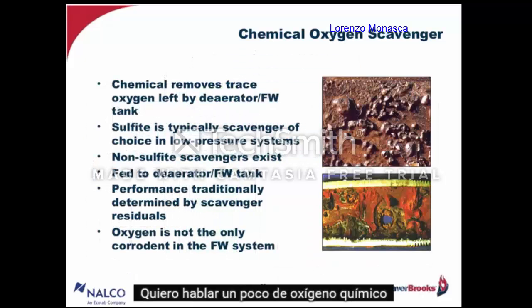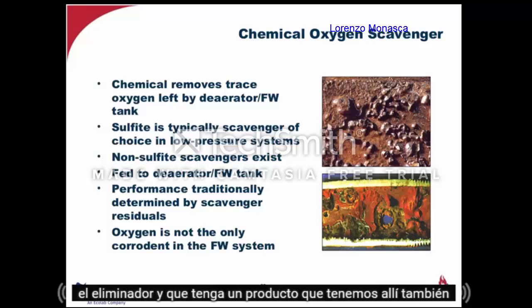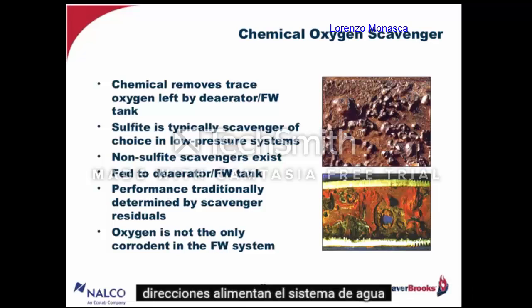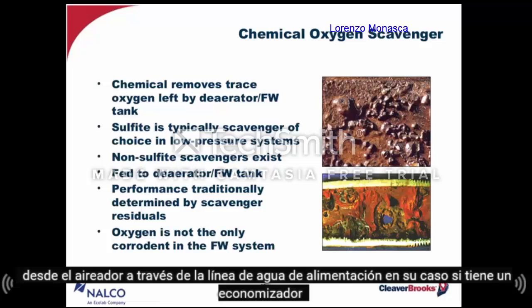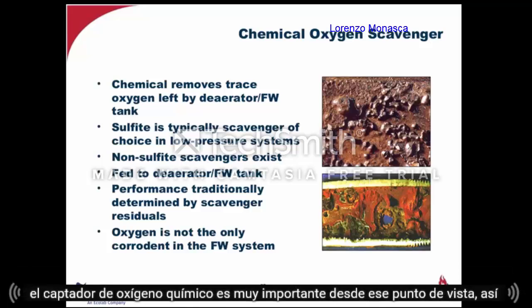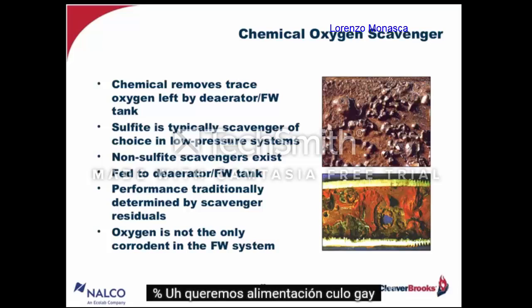So I wanted to speak a little bit to chemical oxygen scavenger and the types of products that we have there as well. That addresses the feed water system, so from the deaerator through the feed water line. If any of you have an economizer, the chemical oxygen scavenger is really important from that standpoint as well.